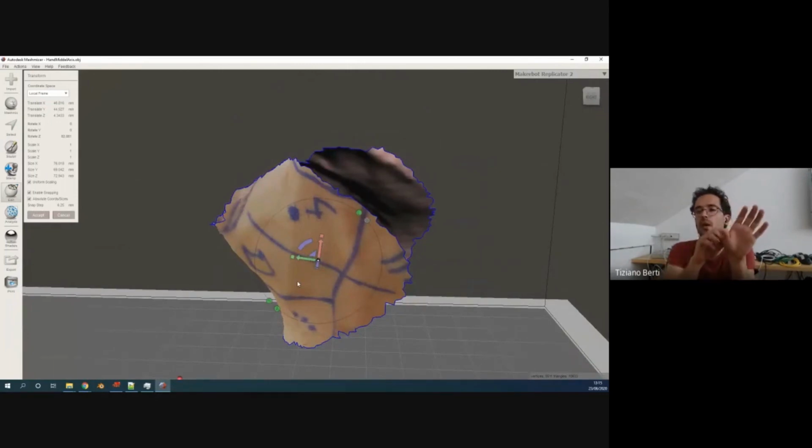Also, if I'm putting in a lot of details like hinges and similar stuff, when I'm on the last part of the process, I start to think, oh, this is a very complex shape. How can I put it into a printer? Then I will choose one direction and correct the small details a little in order to make it more printable. So it's pretty difficult at the end to actually get a correct 3D print for this complex shape.